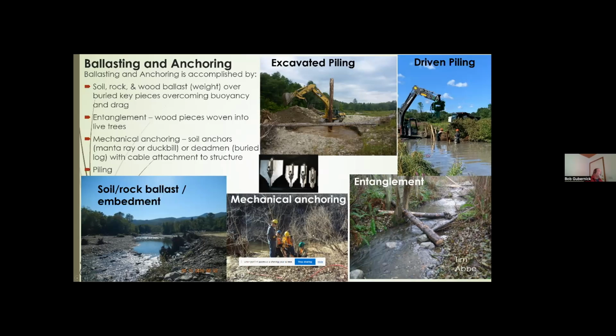Typically you're using a mechanical anchor in a case where you can't use any embedment, it's shallow bedrock, so your veneer of gravel is not very thick, or you don't have any other better methods and you need to have it fixed solidly and not worry about any movement or loss. And that's probably more in urban situations, semi-urban places or immediately above bridge structures, etc.